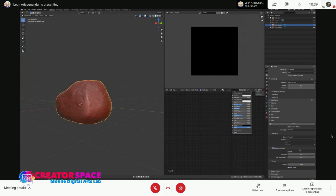The ray distance is how they shoot the rays and how to bake it. If you just use these options, that should give you a good image for your normal map. Now, next thing you want to do is go to sampling. The higher the render samples, the more detail your image has. So in this case here, let's do 500. We don't need to go into too much detail. And then you're ready to bake.